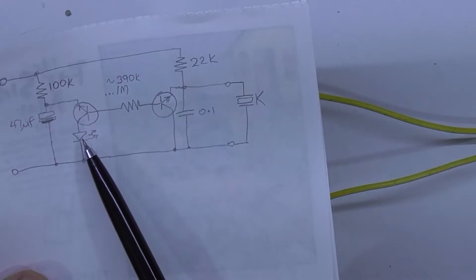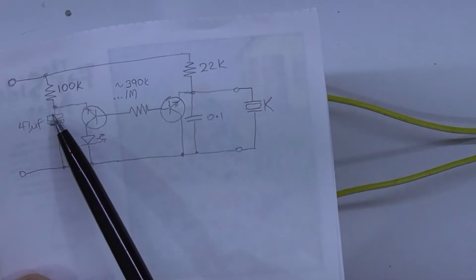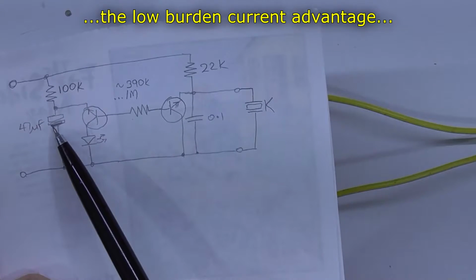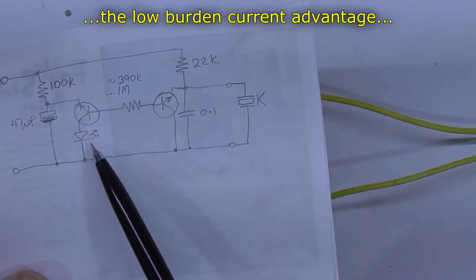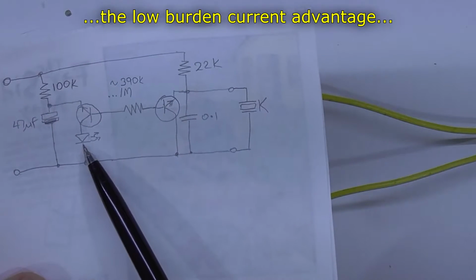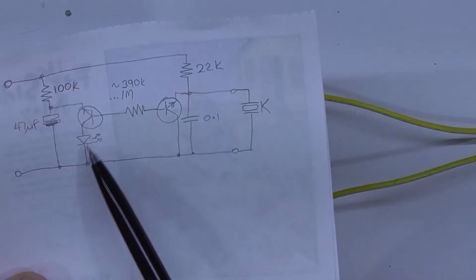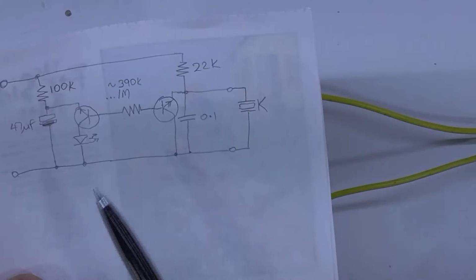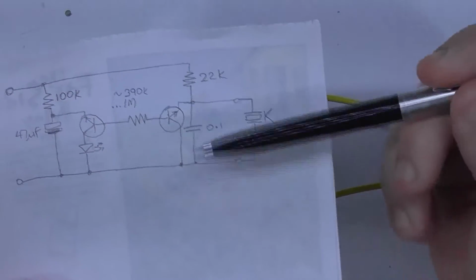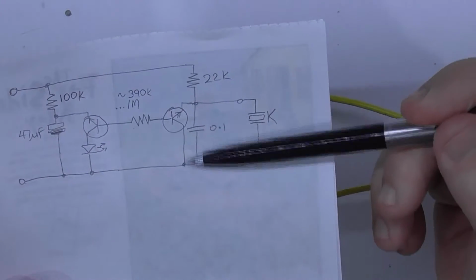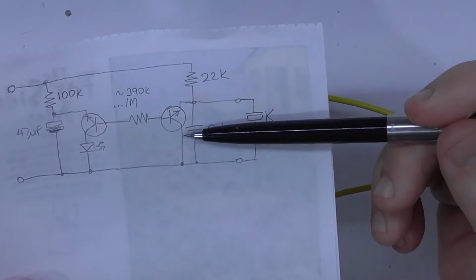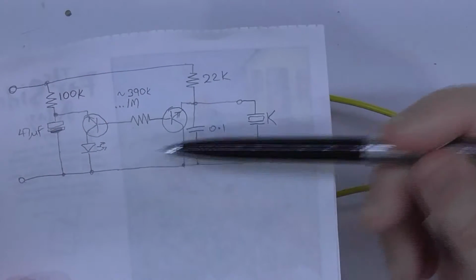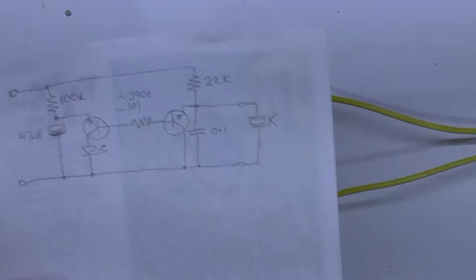And then it became obvious that the advantage that I was looking at of discharging the 47 microfarad capacitor to give me my light pulse unbalanced the collectors, so that hooking the bases up this way was introducing the instability. So what I needed to do was to put a load, or make the collector circuits equivalent between the two.